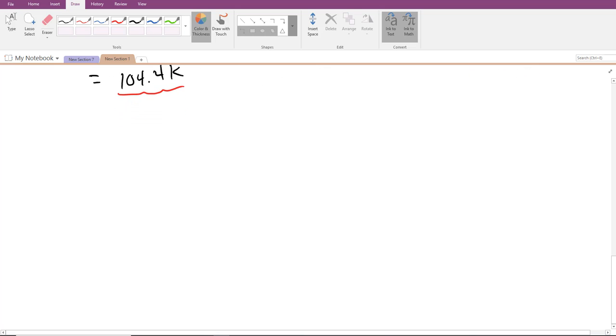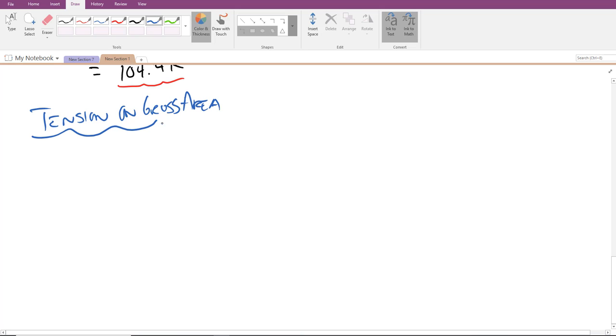All right, now we need to check our tension failure, both on the gross area and the net area. So we've got tension on the gross area first. That is failing through the plate. And recall the equation for this. There's our actual stress side, our allowable stress side. We'll go ahead and just substitute that in straight away. 60% of the yield stress.